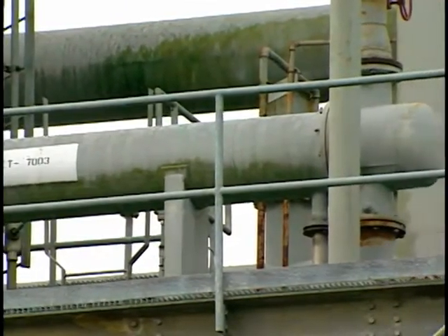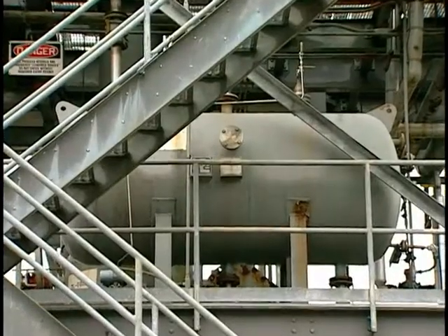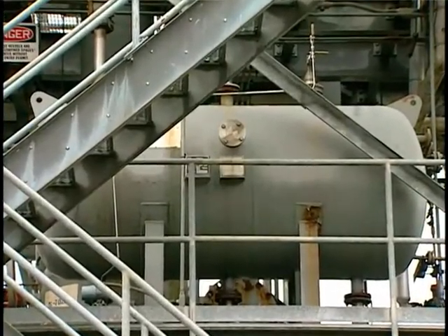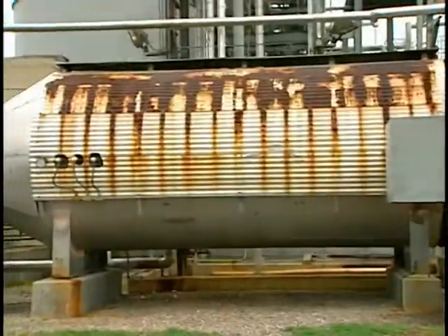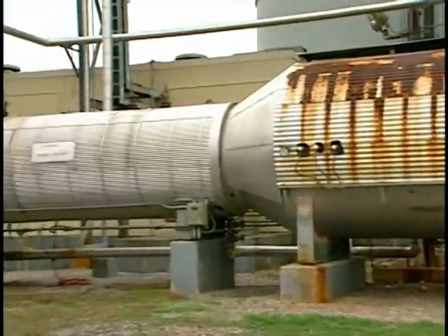The recovered condensate is separated in a decanter to recover the organic compounds, which are either returned to the process or incinerated to recover their energy value. The non-condensable organics exiting the condenser are usually incinerated.